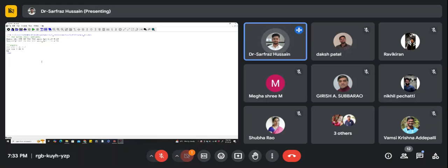Then next I want to give the input. So Vin is IN and 0. And here I can give any sort of input. It can be a pulse, it can be something else. So let us use a pulse input. In the pulse, I can give a definition here. So what will be the definition of the pulse? What will be the lower voltage? What will be the higher voltage? All those things we need to define. If you are giving a pulse, let's say the low voltage is 0 and the higher voltage is 1.8. Then what is the period? So let's say you don't know what values you will write here.